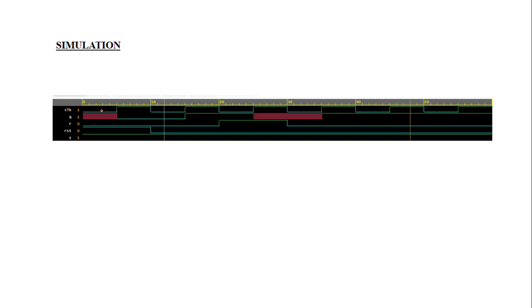You have to observe here. See the first one: the passage of clock. Whenever the passage of clock happens, only then is the simulation ready to execute anything. Until that, it simply takes the value as unknown. So that's why it shows red color. Red color means unknown. Whenever the positive edge happens, only then does the simulation happen. Otherwise it simply considers it as unknown, so you can simply say Q is red. Red is nothing but unknown.